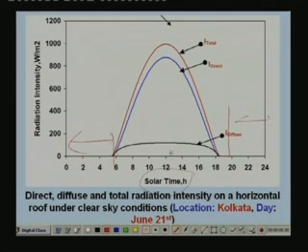They reach a peak at solar noon, then gradually decrease and again become 0 at sunset. So it is 0 at sunrise and 0 at sunset, continuously varying throughout the day. Because of this, the outdoor radiative boundary condition also varies continuously with time.